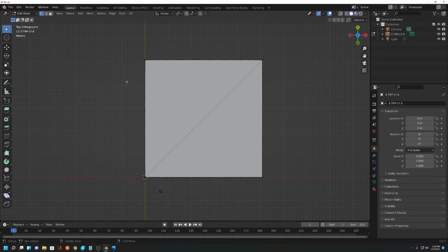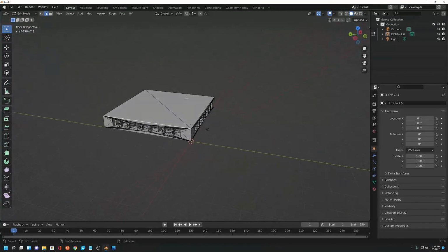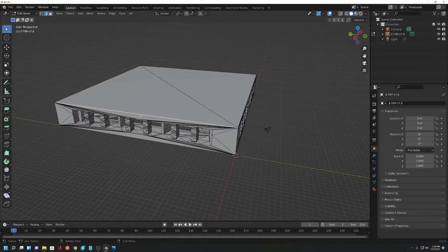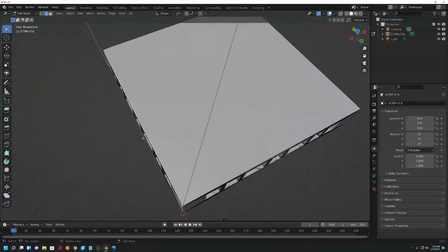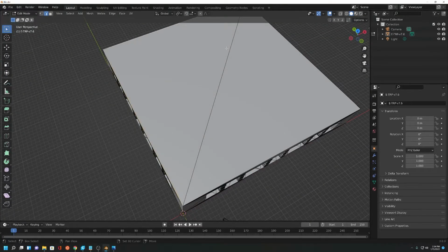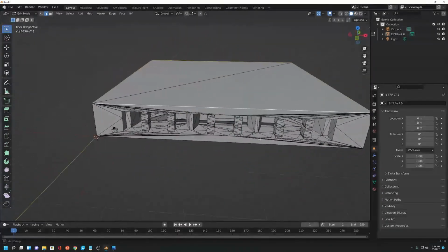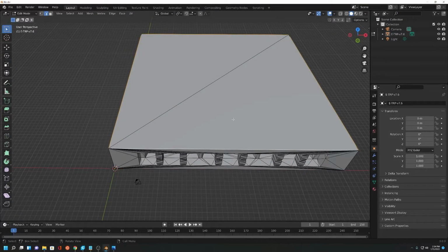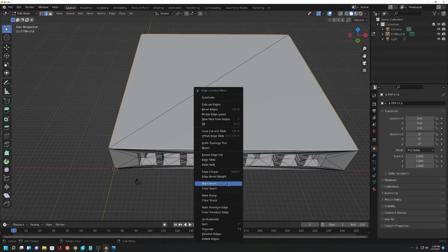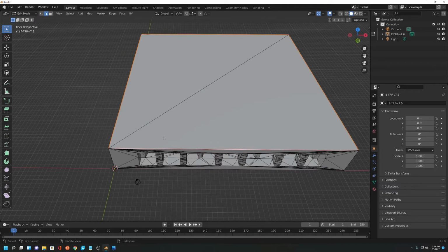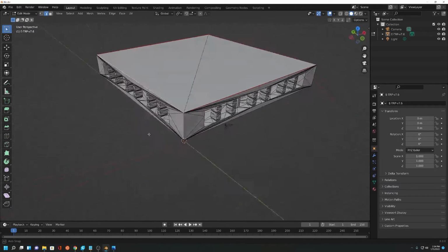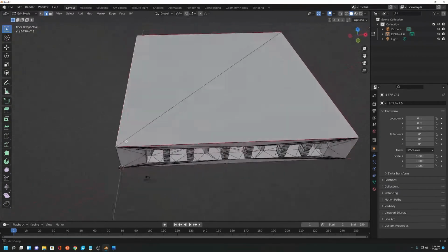In order to get the proper texture on here, we're going to hit edge select, and then we're going to click here. You'll notice that once we click it, there's a small little white line at the area which we chose. Now from there, just hold down shift, click the other corner, click another corner, and click another corner. Now all 4 corners are highlighted. So what we're going to do now is right click in the open area, and we're going to go mark seam. What this does is clearly mark our location, shows them all sitting right there, very nice and neat.